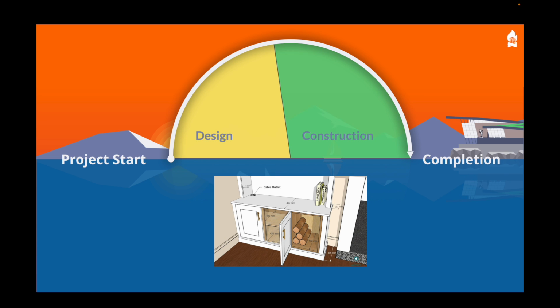So another way of doing it is to go further at the design stage, draw the doors exactly to size with the gaps taken off, figure out the overlaps of those oak parts, get everything absolutely pinned down, so you're really just following a set of instructions when you manufacture. And that should, in theory, reduce the construction time.